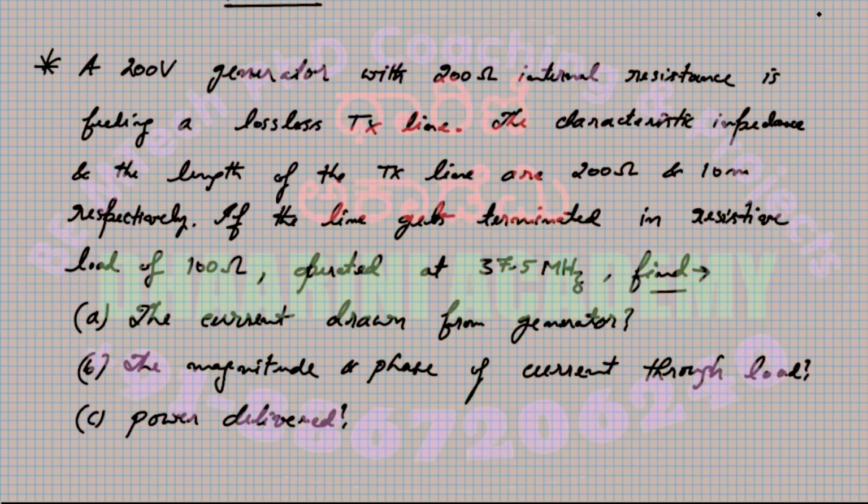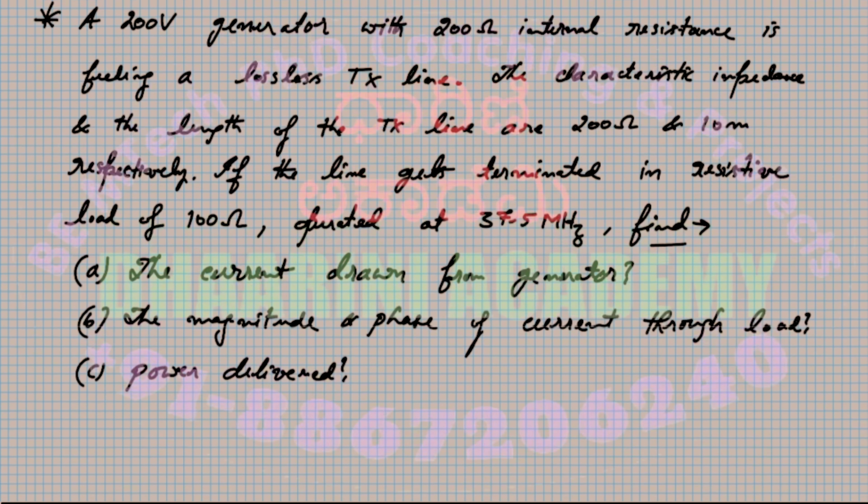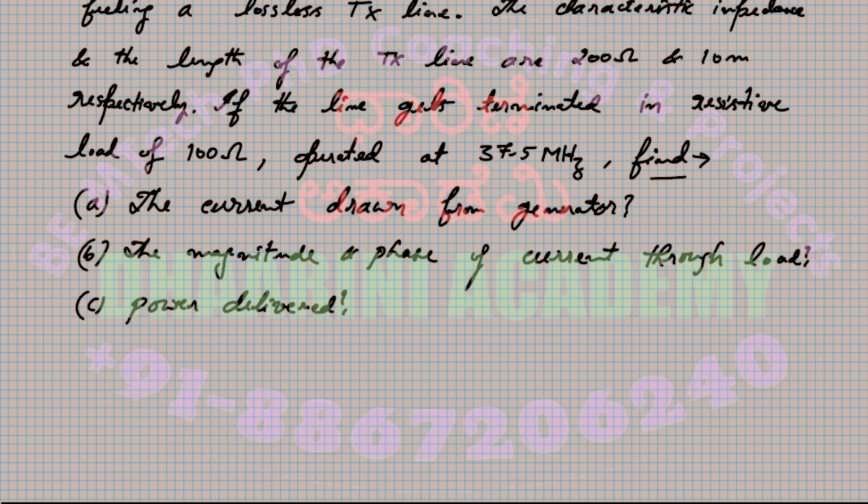Whenever a value like this is given without mentioning any other parameters, if a voltage or current is given with respect to a supply, we know that it is a root mean square value, correct? I'm taking this concept directly from basic electricals. Wherever a voltage is given as it is, it means it is the RMS value. So that's the first thing which we need to remember.